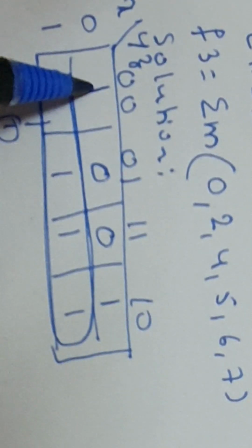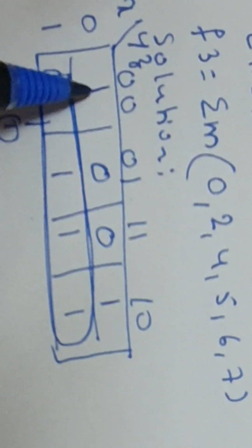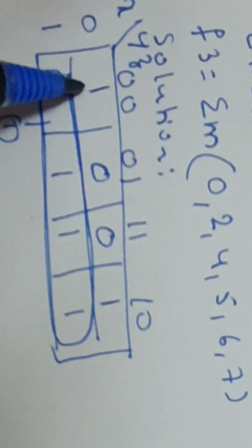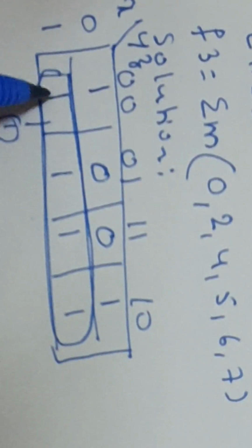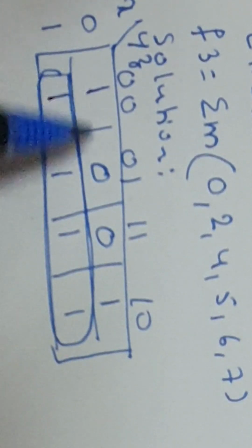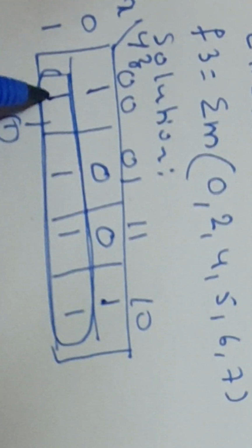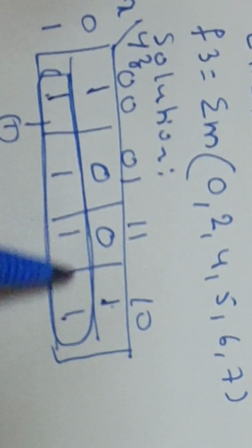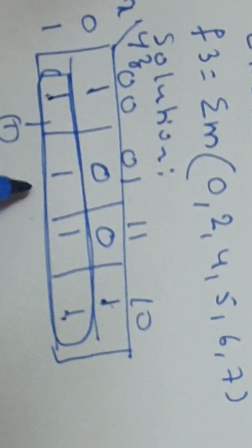Then how to cover this? Now, is an octet possible with this? No. Next, we should not suddenly jump into a pair with this. Think whether a quad is possible. Now this and this are adjacent. This and this also are adjacent. This and this are also adjacent. Hence these 1, 2, 3, 4 are all adjacent, hence they make a quad.